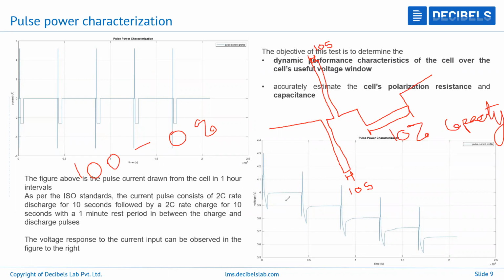That is observed in the voltage graph, which I will come to in just a minute. That's the importance of this pulse. It helps analyze how quickly the cell would respond to this kind of pulse input. And then the next discharge pulse is basically meant to remove 10% of the capacity, which means it's then brought to a lower battery life.